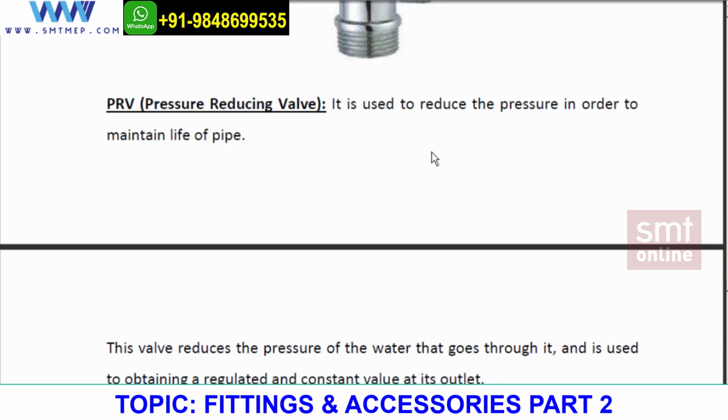The same kind of thing happens over here. As the water is coming down from the 30th floor, 30, 29, the pressure keeps increasing and increasing. And I'll be getting such a huge pressure that it is not at all recommended as per the standards and codes, and those codes are IPC and UPC, which we do follow.